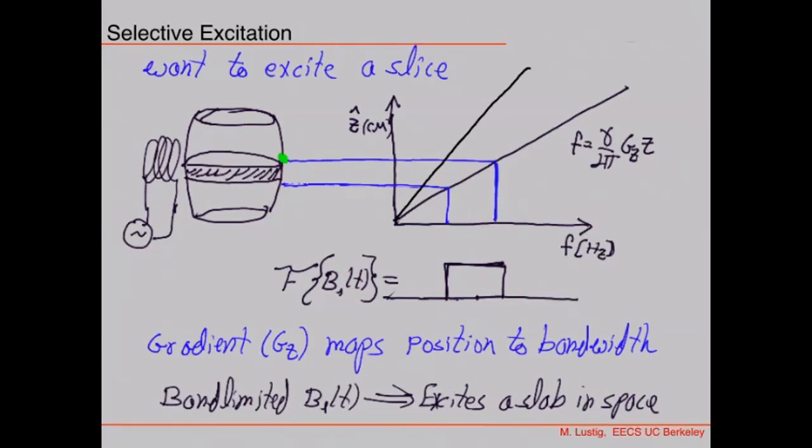And the reason I only gave you 8 points is because, yes, the envelope is a sinc, but it also needs to be modulated by some center frequency, right? It needs to be a sinc that is modulated by a center frequency around a certain bias, because if I just do a sinc, then everything will be around 0. So it's a modulated sinc.